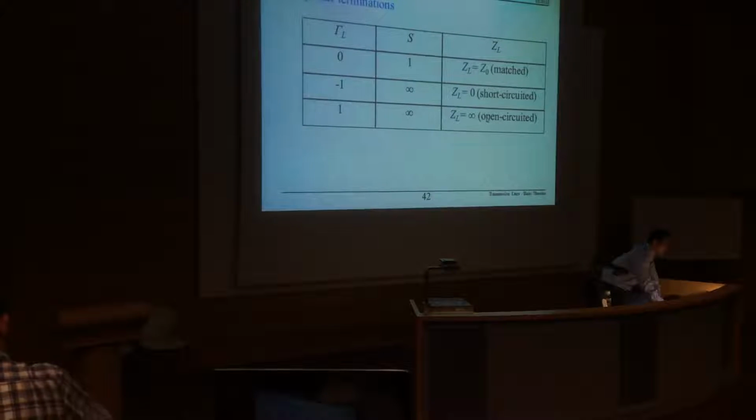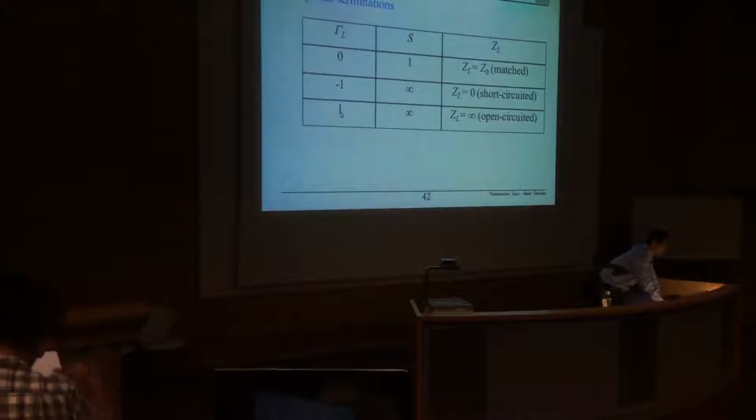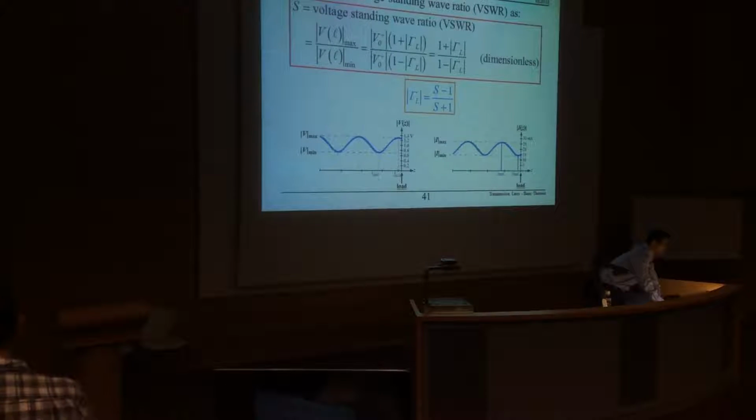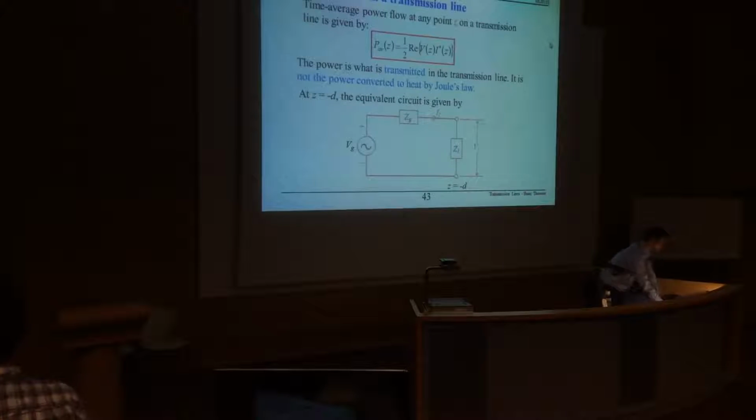Here we mean the load is matched, or short circuit, or open circuit. If it is an open circuit, the reflection coefficient is +1, and again the standing wave ratio is infinity. Actually, the standing wave ratio range is from 1 to infinity. Standing wave ratio will not be less than 1.